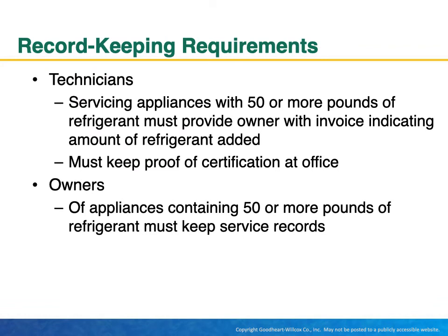Record keeping requirements. Technicians servicing appliances with 50 or more pounds of refrigerant must provide the owner with an invoice indicating the amount of refrigerant added. Must keep proof of certification at the office. Owners of appliances containing 50 or more pounds of refrigerant must keep service records.